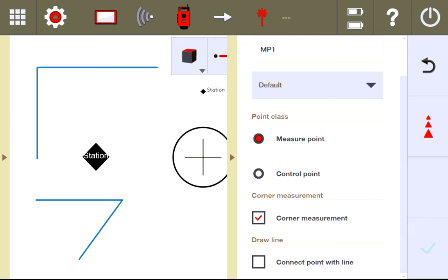None of that matters. The problem that we run into when we measure a corner is that whether we use the optical or the laser, it's hard to know if we are looking dead on the corner itself, or if we're, for instance, accidentally on one of the side walls when we make that measurement. It's a tiny gap to make sure we're accurate on hitting the corner. But of course, when we measure, we want to be dead on as possible. So the tool's going to ask for two measurements to make sure that this is done accurately.